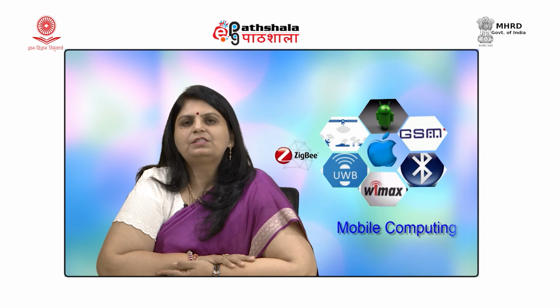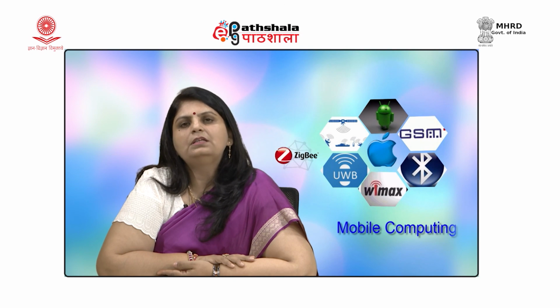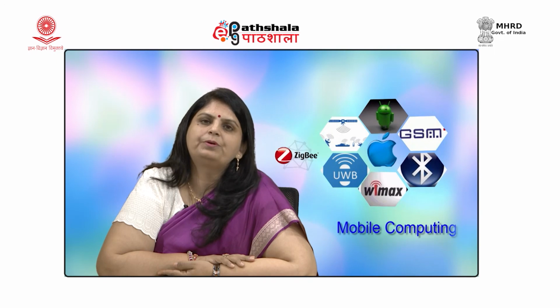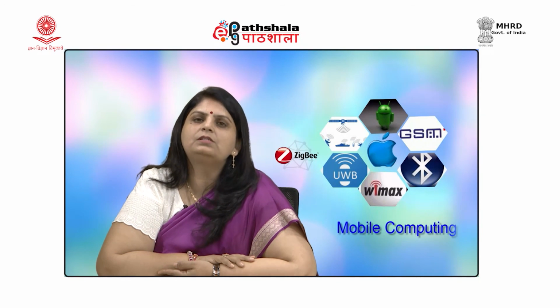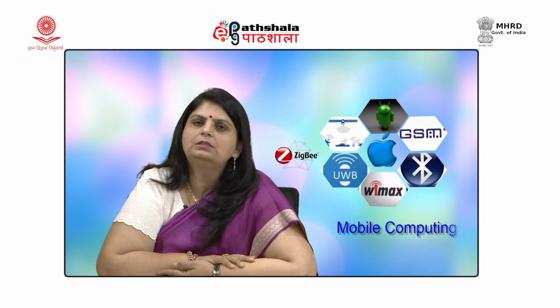So, to summarize this module, we learnt about the signal propagation effects. We learnt about the three modes of propagation of the signal when it travels from transmitter to receiver, that is the ground wave propagation, which is used by signals of low frequency, in which the signal travels along the ground.